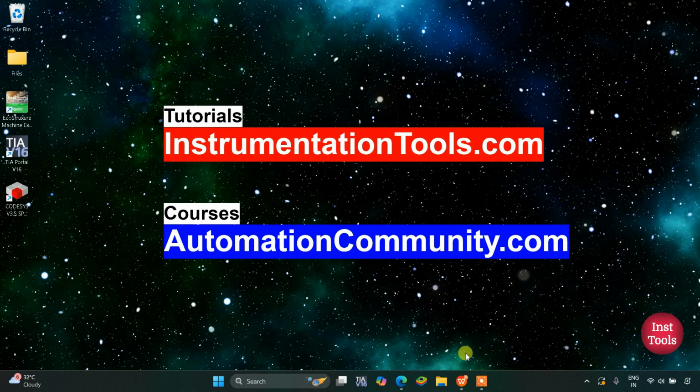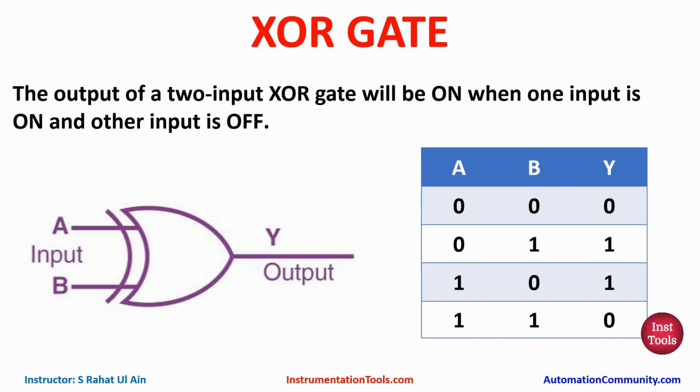Today in this video, we are going to discuss derived logic gates, that is XOR and XNOR. So let's start. XOR gate. The output of a two-input XOR gate will be on when one input is on and the other input is off. As you can see in the table, the output Y is on when only one input is true. Then only output Y will be on.